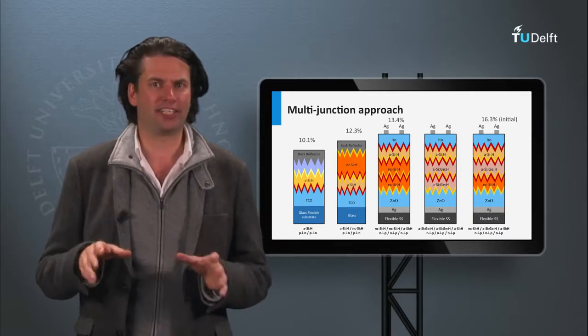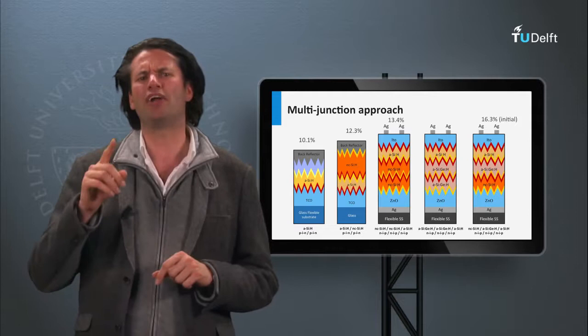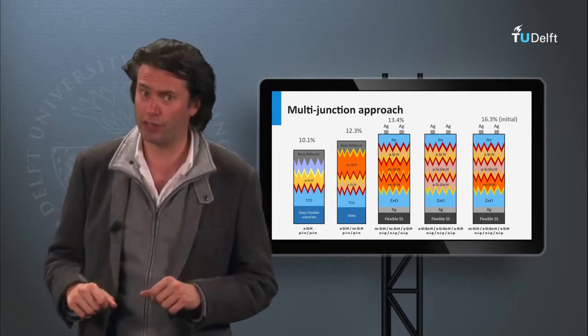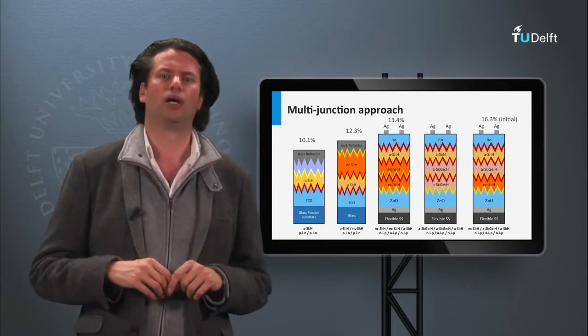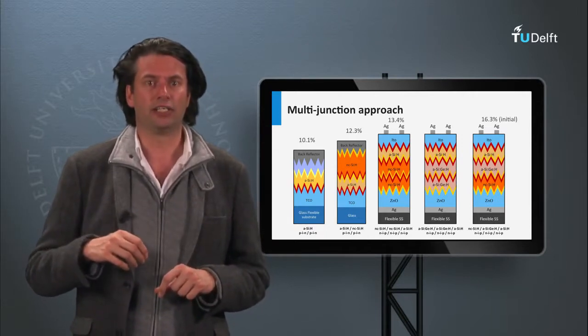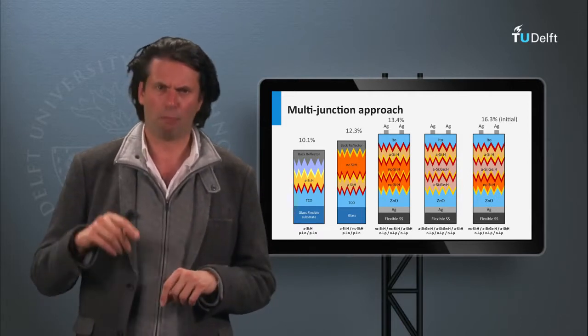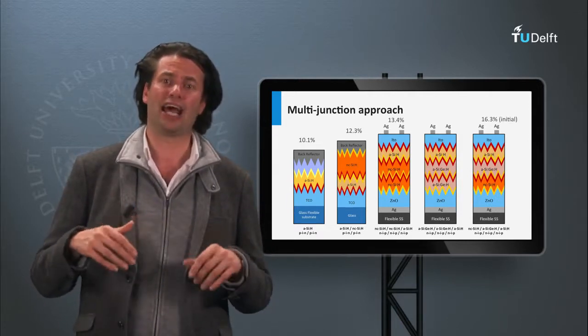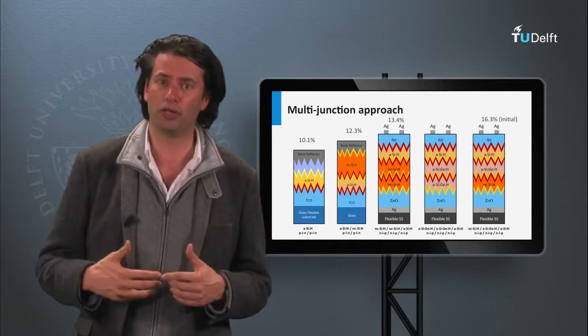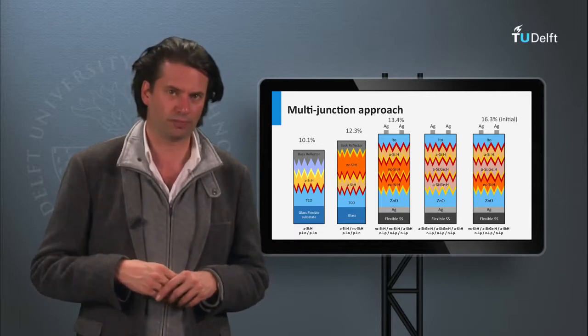The light-induced degradation, also referred to as the Staebler-Wronski effect, is one of the biggest challenges for thin film solar cells. The recombination of light-excited charge carriers generates some metastable defects in the absorber layers. More bulk defects means enhanced charge carrier recombination in the bulk, which mainly affects the performance of the amorphous solar cells.